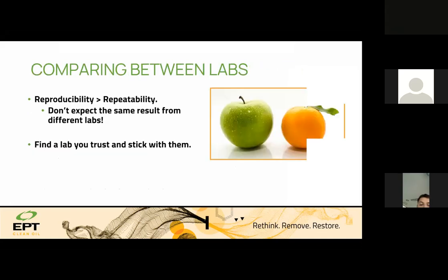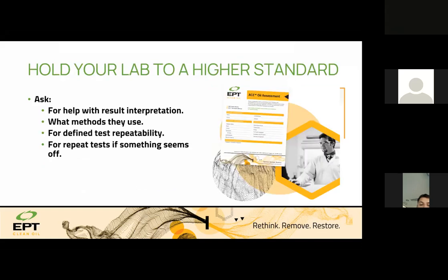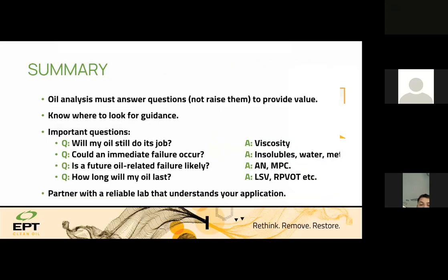And then remember about, for example, acidity. We discussed the total acid number and the different tests, which were titration, Karl Fischer or FTIR. Don't compare the results of different tests, do the right test. And then I recommend using the very professional lab of EPT, which is in Canada. Many oil samples from around the world from turbomachinery are being sent to the lab. Our lab is not a commercial lab. We focus on turbomachinery, and we develop the tests. It's an R&D lab, which can support you.